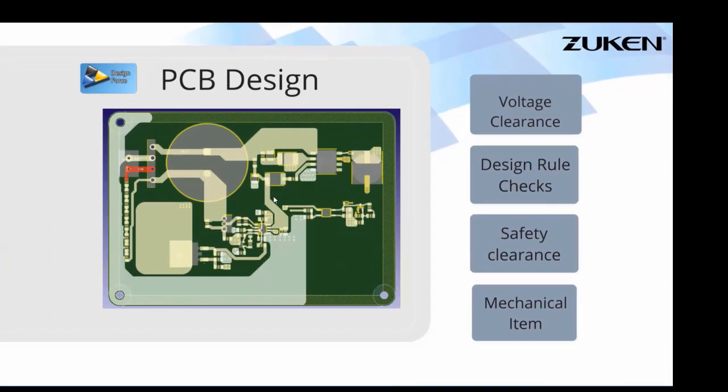Next, we turn our attention to the PCB design. I've chosen a flyback converter circuit as this is a natural barrier in areas of high voltage, which can clearly demonstrate CR-8000 capabilities to adhere to set constraints. I will demonstrate how to set up IPC 2221 settings for uncoated conductors on external surfaces, run design rule checks, and show how to validate your design.